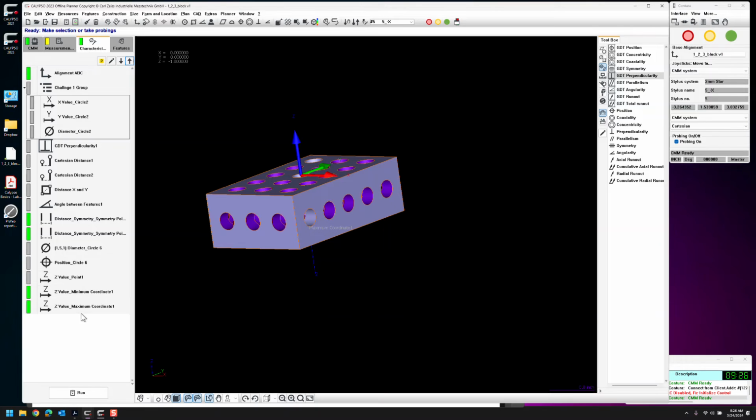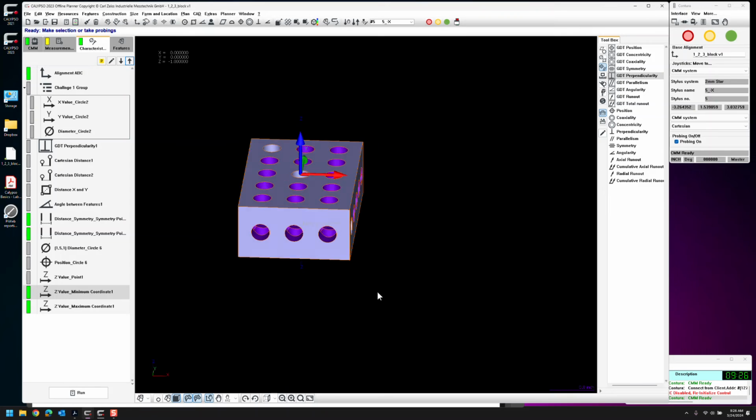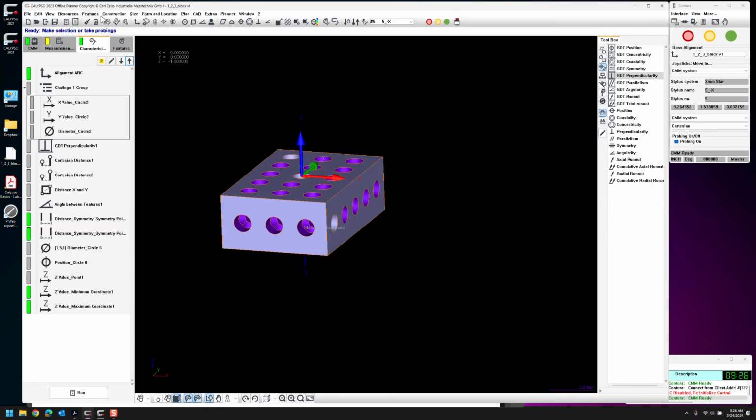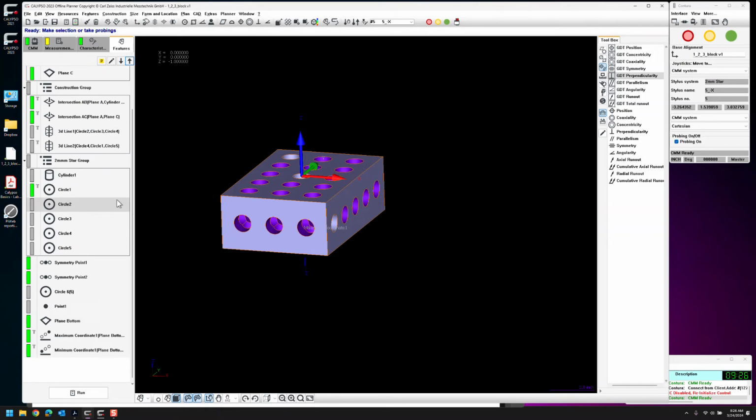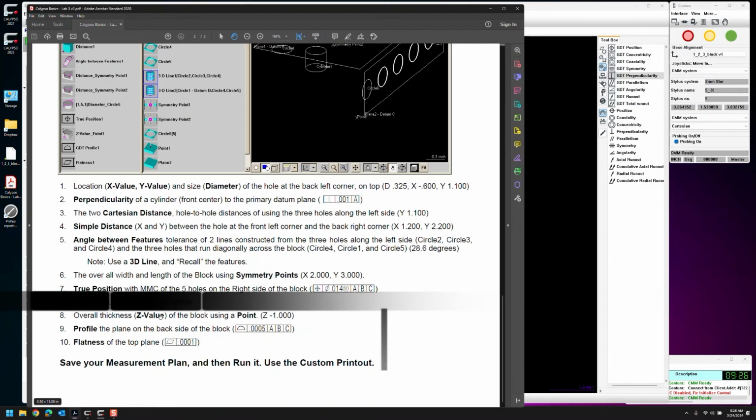We also have an average value. By the way, this average value should be somewhere between my min and max. If it's too much closer to my min or too much closer to my max, then I know that there is something funny going on with my data, my measurement, my part. Somewhere, ask questions. Sometimes that's why we want to get multiple outputs, because the differences in the multiple outputs hint to us that there is a problem.